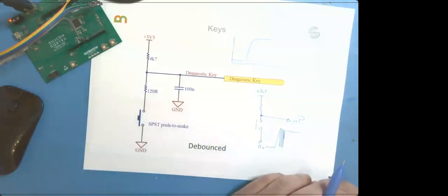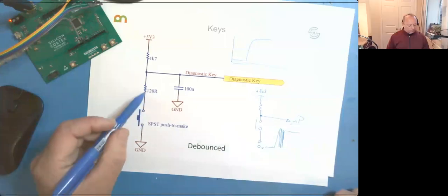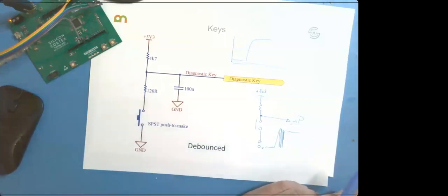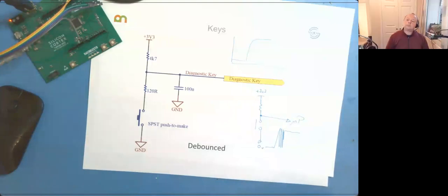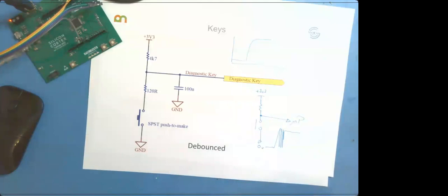Stephen? Yep. Two questions. First is, why the extra resistor in your printed case rather than the simple one? And the second is... this one. Yeah. Well, actually, the second isn't so much a question as a statement. If you're going to do software debounce, that takes the form of basically sampling the input line lots of times over a period of something like a millisecond, and waiting until you get a fairly consistent output from that process. So, if you get far more ones than zeros, then decide that it's a 1.